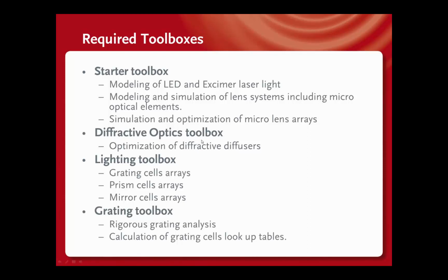The diffractive optics toolbox is good for the optimization of diffractive diffuser elements. As I mentioned, the starter toolbox can analyze homogenization systems with diffractive diffusers, but if you want to optimize the diffractive diffusers, you need the diffractive optics toolbox. The design and simulation of grating cell arrays, prism cell arrays, and mirror cell arrays is included in the lighting toolbox.